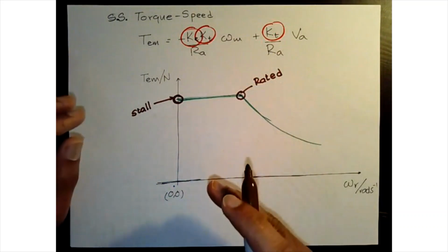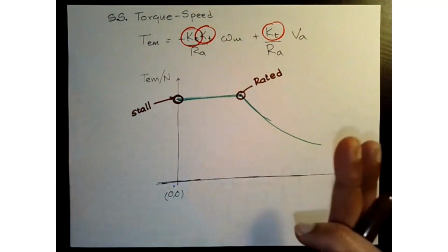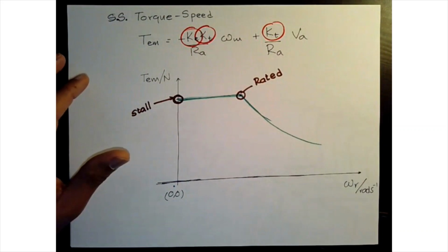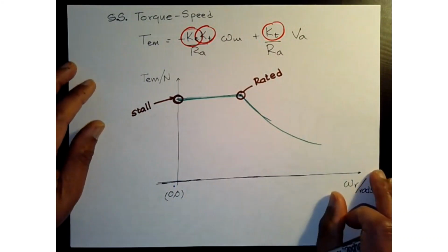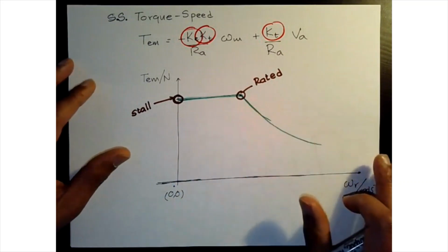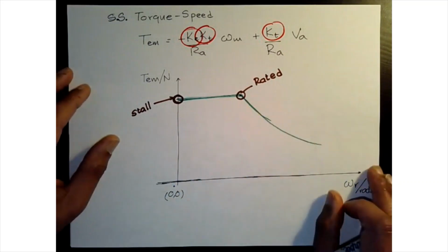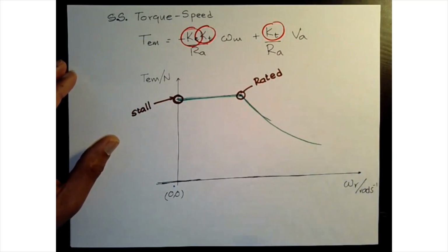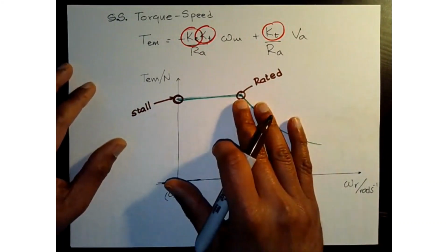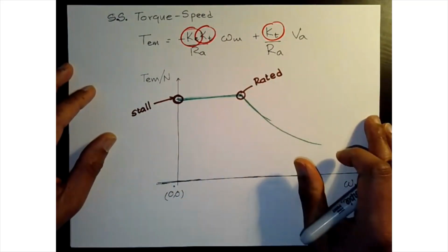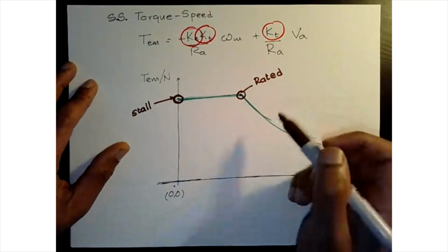Now, typically, for a good engineer, when you select this, you're choosing with certain safety margins for your motor to continuously operate, given the thermal capability of your material and your system. All that has to be taken into consideration. There's some flexibility there. When you design, you don't get exactly where you want it to. So keep in mind, this is not going to be set in stone for a motor. You change your cooling system, this point could change.